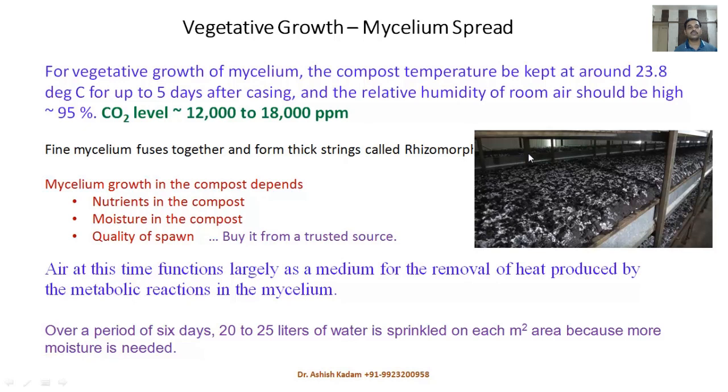So you have to ensure that when people go in, they have a breathing mask. They should have an oxygen cylinder filled with the right quality and right quantity of oxygen, with a breathing mask. There should be a proper register for the people who have entered the growing room, so that you can track how many people are working in the growing room.